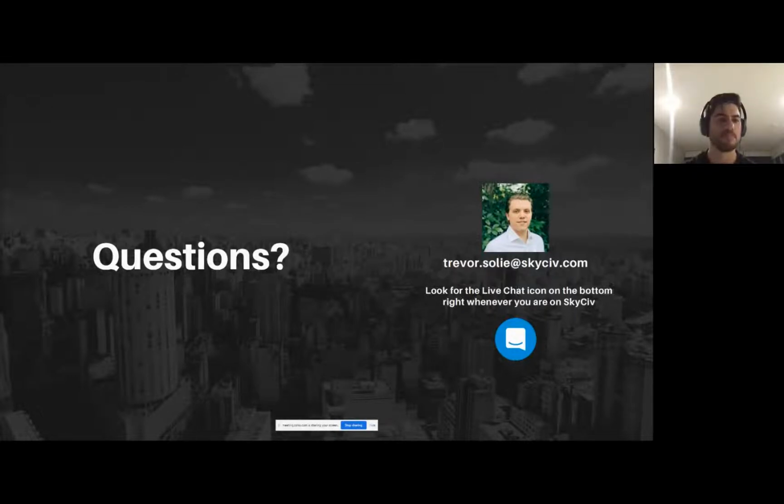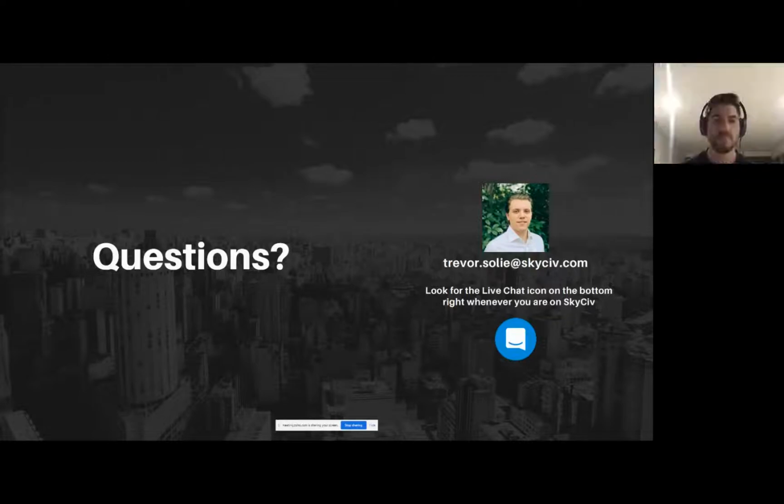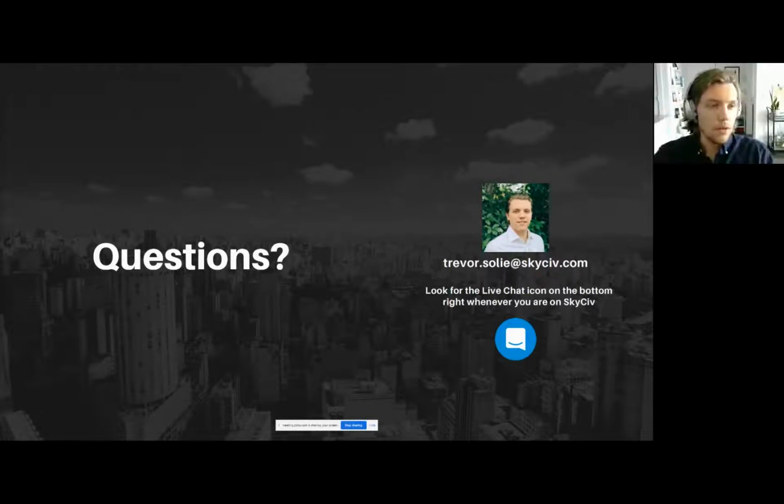Yeah, no, that's definitely a perfect commentary. I was trying to mention the end nodes of a member. If you try to shift either one, the member will shift with it. But you're definitely correct. If you wanted to, let's say, shift a member that has a bunch of members connected to it and make it a slope, then yeah, you'd want that member to be continuous for those connected members to also shift with it. Yeah, definitely. Next question here.